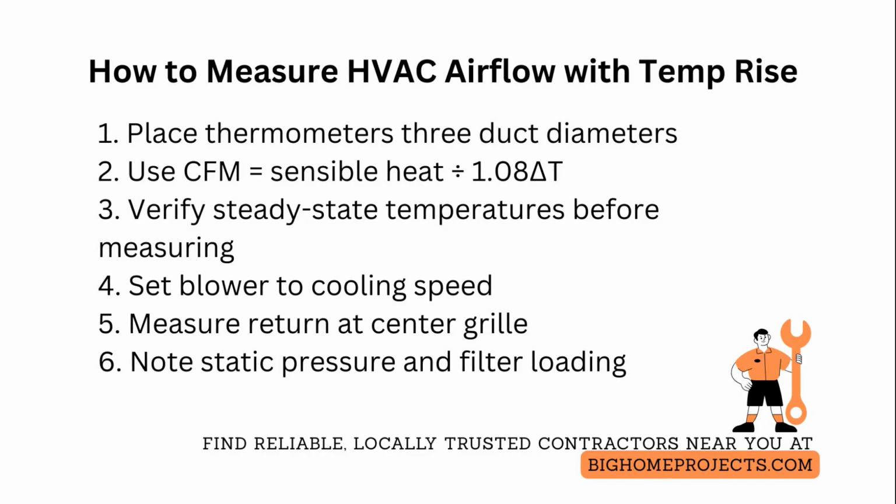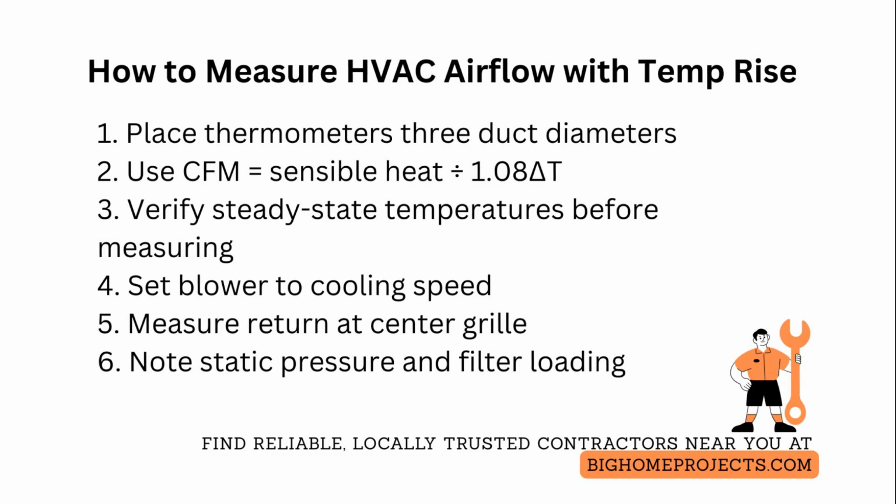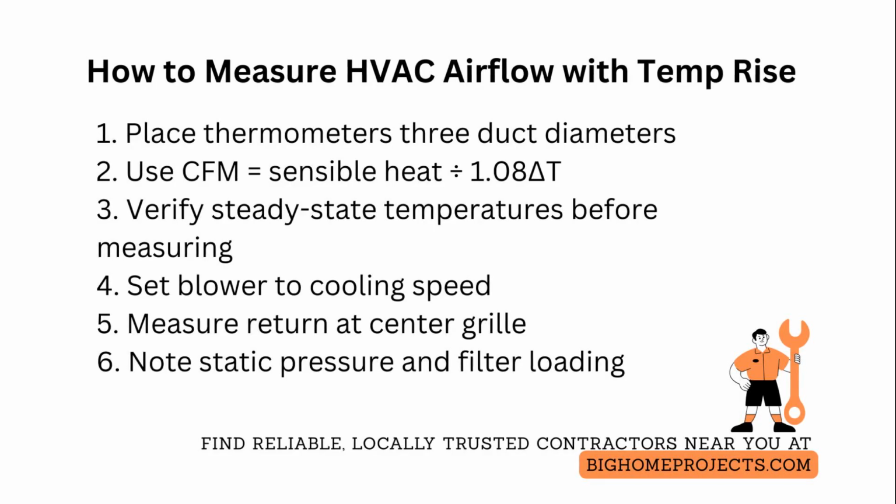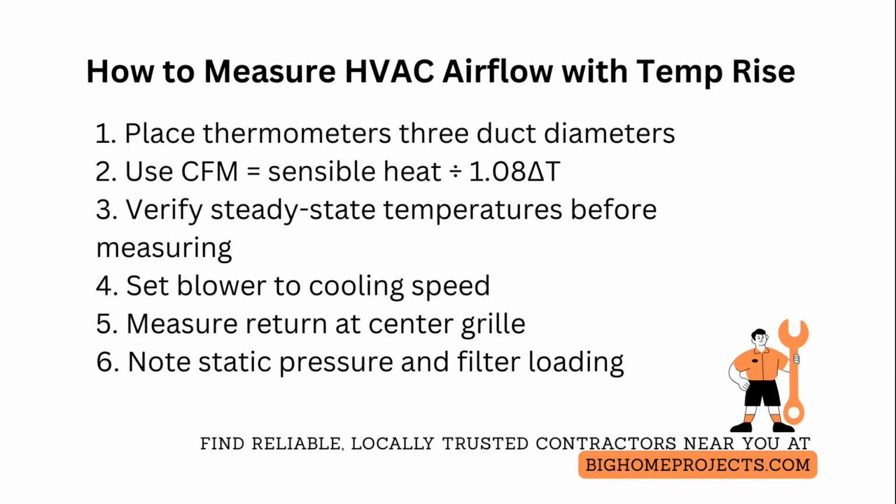Document ambient conditions, equipment serial numbers, and blower tap positions so results are repeatable. Convert airflow adjustments to blower tap or variable speed settings and retest after every change, because motor characteristics and system resistance produce nonlinear changes in cubic feet per minute.